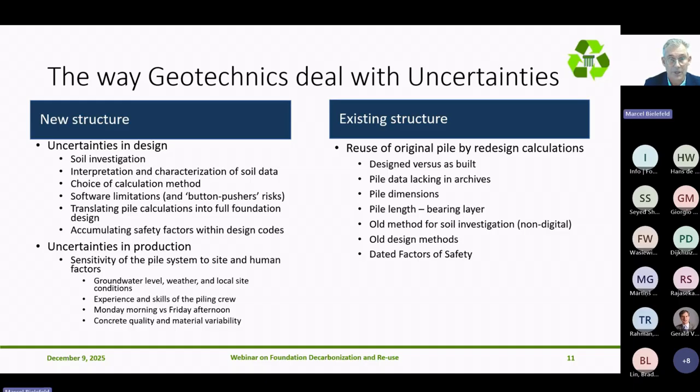And then if there are older piles, the old methods for pile design are outdated. They are not up to date anymore. Nowadays, I assume our methods are much more detailed and much better. Same is true for soil investigation methods, either SPT, CPT, or laboratory tests. Old CPTs and old SPTs were all based on just ordinary data. Nowadays, it's all digital, digital files which can be read by the software. So even if you do a redesign for an existing foundation, that comes with uncertainties as well.